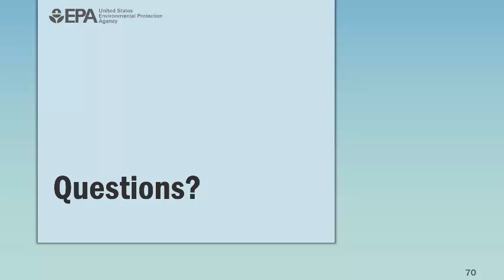Thanks. A question about, early on you were talking about a gridded approach to HRUs. Could you expand a little more on that and how SWAT deals with that? Okay. So let's say, for example, you want to take your watershed and overlay a grid on top of that, and we are developing GIS tools to automate this whole procedure, so the next release of the interface will be able to delineate your watershed on a gridded basis, so that every grid has a channel process, because in SWAT, the subbasin and channel process are intertwined.